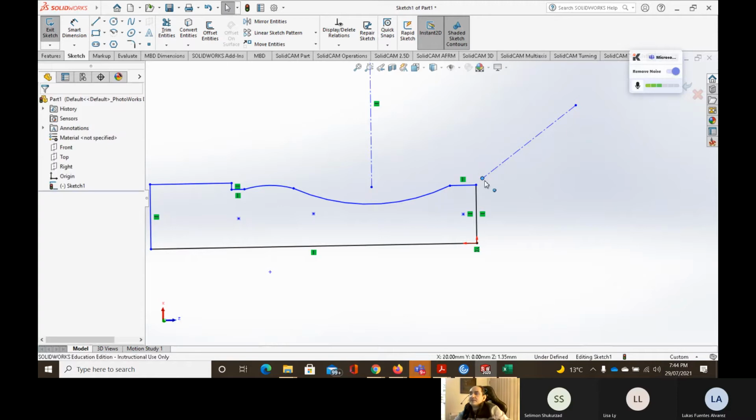Okay. Now my cutting tool is in this position, and the first thing I will do is remove a layer from the face. Again, because when we prepare the part, the top surface is not going to have a good surface finish. So we do a process which is called facing. In the facing, I will bring my cutting tool to the end here and then send it toward the center.